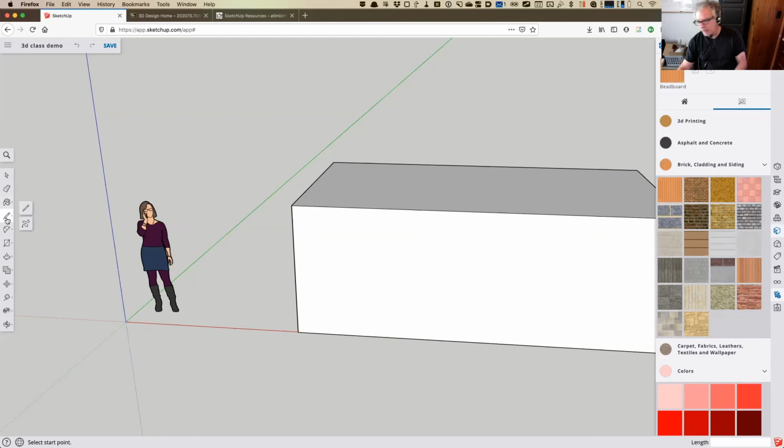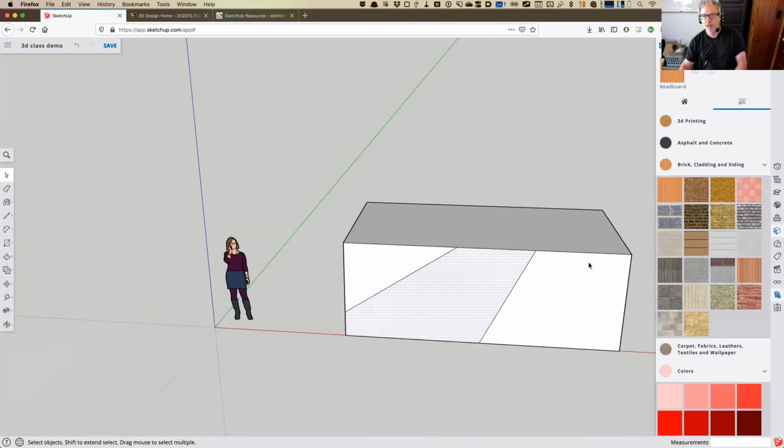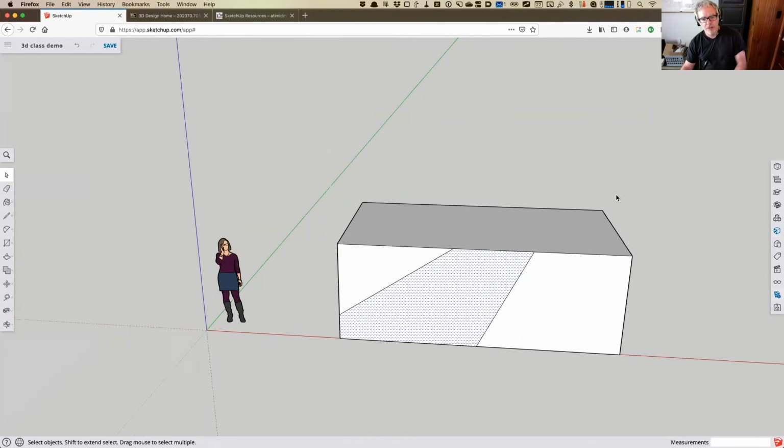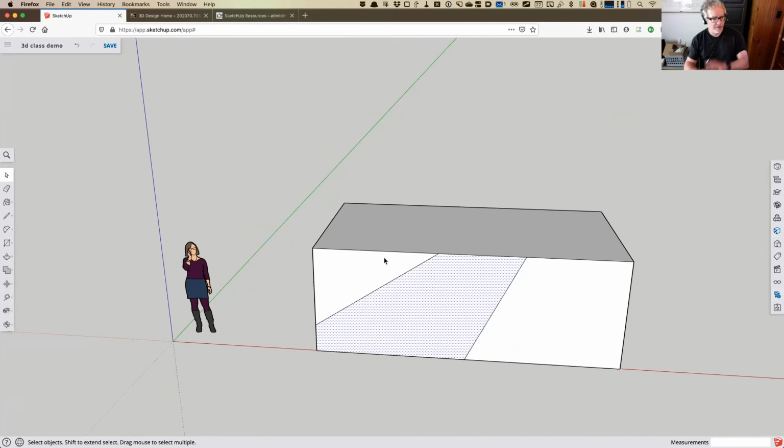Right below that is our line tool. We have two kinds of line tools: a straight line tool and a freehand line tool. So you just saw me use the straight line tool. I can pick a surface and draw a line between two points by clicking. Now I'm not holding down the mouse. I click once, then I find the other point where I want the line to go and click again. If you notice, when I did that, it now makes a separate plane, because I have another shape here. So SketchUp works between lines and shapes and later on forms. Everything is tied together.